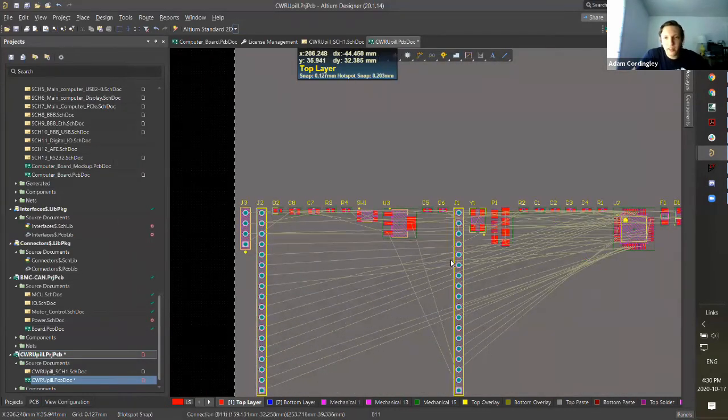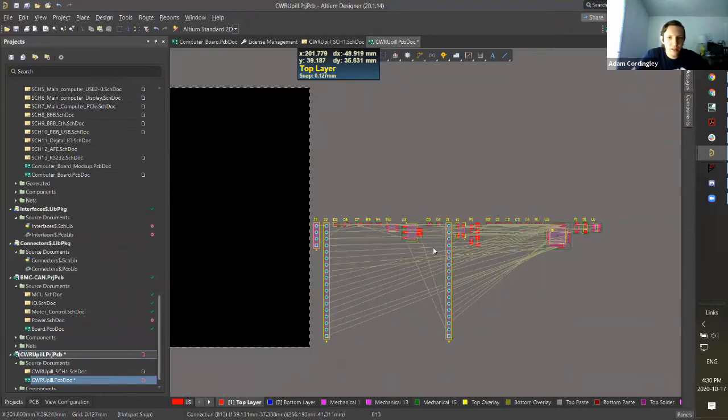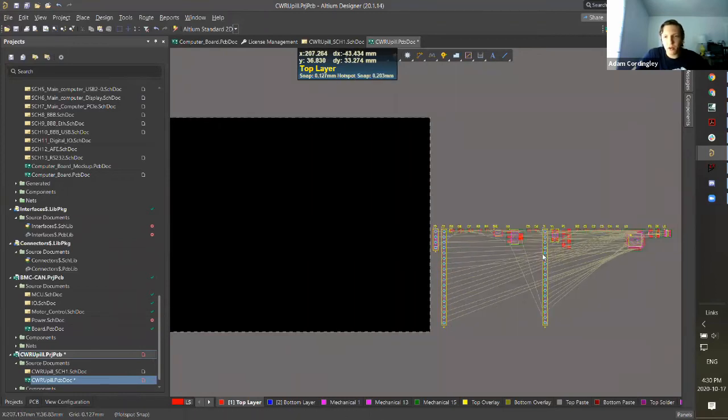All right, let's take a breath. Now we've done all of our setup. We can now start doing things like positioning components. Usually PCB layout or design breaks down into 2 stages. Your layout, which is positioning all the components, then the routing, which is connecting the parts together with copper. And I'd say your layout stage takes 90 to 95% of your time, and the other 5 to 10% is spent routing. So you can use that as a predictor of your time spent.